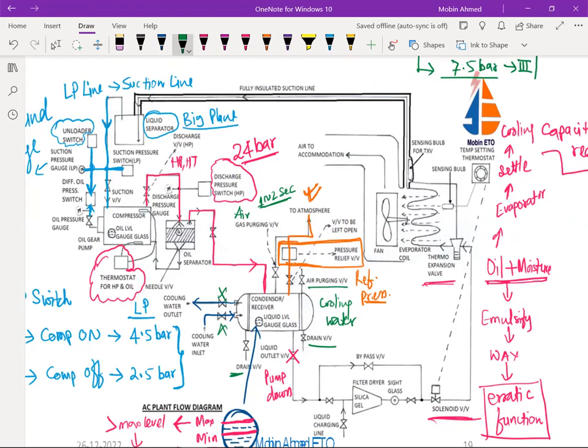After the boxing up, generally we open the inlet valve. This valve is opened first. This remains closed. Okay, and we open the drain valve, so all the air will be out through this. Once it is draining, we close this drain valve. Then whatever air is there is going to purge out. When the water comes out from this air purging, we open this one. This is how your air is purged. So you need to do it this way.